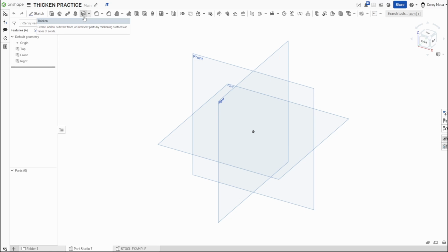And there's nothing today that we're going to show in this video that you can't do with extrude. It's just another way of going about doing it. If you're coming from SketchUp and you've ever drawn some stuff on the old SketchUp program, you had to draw and extrude a length and then change the length of whatever piece you were doing if you were doing some woodworking stuff. That's kind of how the Thicken tool works, and we'll go through there.